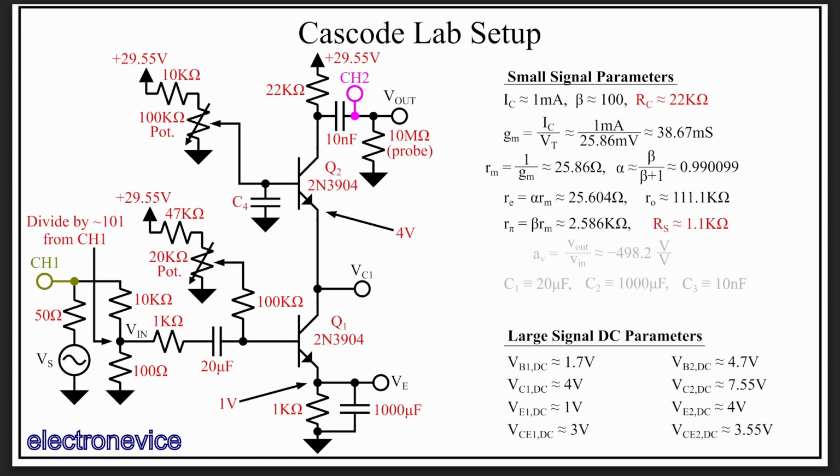So I will make one note here. We're making some approximations here for the gain, assuming that the whole current gain of the common base equals 1, which only occurs if we assume alpha is approximately equal to 1. So I'm not going to go into all the slight deviations that occur. They are small enough that we can ignore them. So the gain remains the same as in the common emitter, as expected.